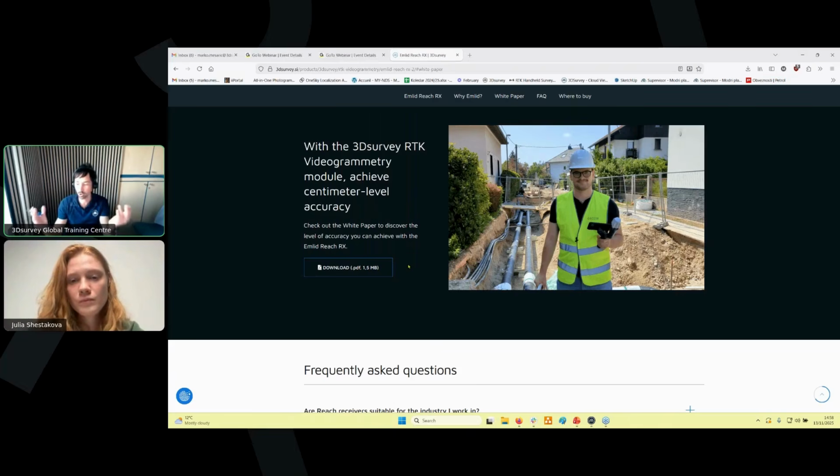So actually you use both those apps. First you run N-Trip and connect; the first time you need to predefine your connection settings and so on. Next time you just connect to corrections, and then you start the 3Dsurvey SiteScan and it works.